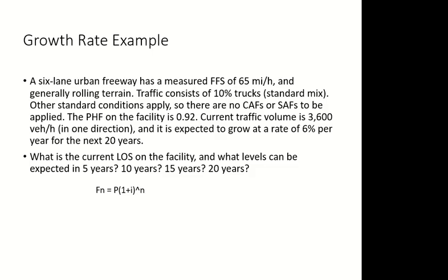Current volume is given. The current volume increases 6% every year for the next 20 years. So next year will be 6% more, then 6% more, then 6% more. The rate will continue for the next 20 years, not the value. The value is changing every year. By how much? 6%. For how long? 20 years. What will be the level of service for the facility now, and then after 5 years, 10 years, 15 years, 20 years?